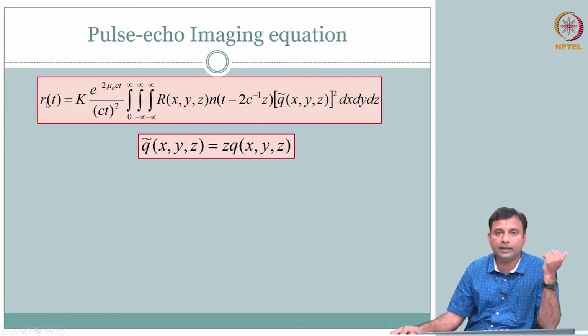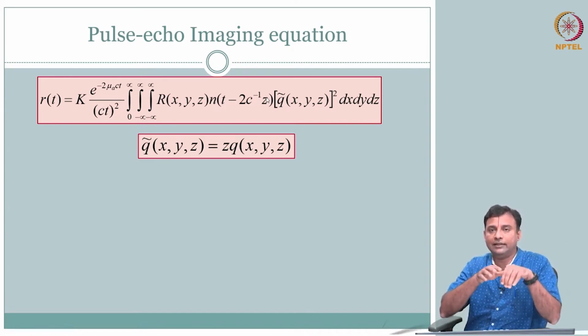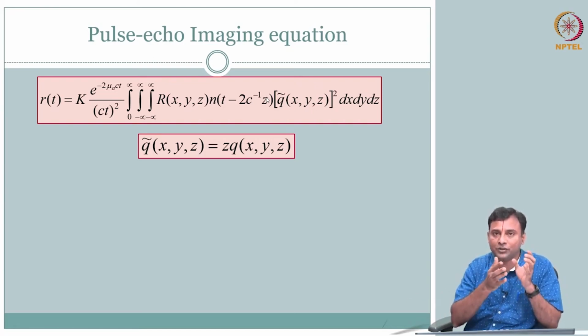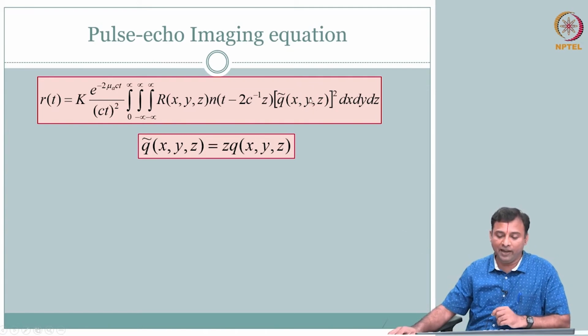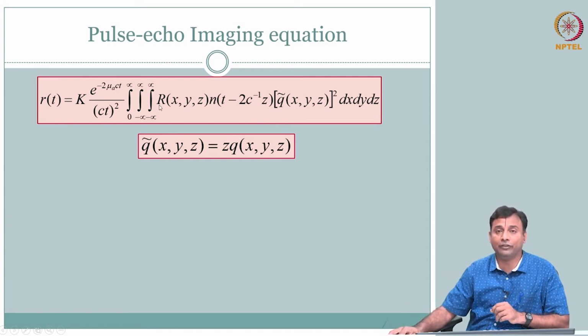So you send a signal, you get the echoes back, and where the ultrasound wave is hitting after you send it out of the transducer depends on the beam pattern, right? Near field, far field. So wherever it is hitting, whatever is the reflection coefficient at that location, that amount will come back and you get a net sum. So at every time point you have a signal, and this is your signal that we talked about.